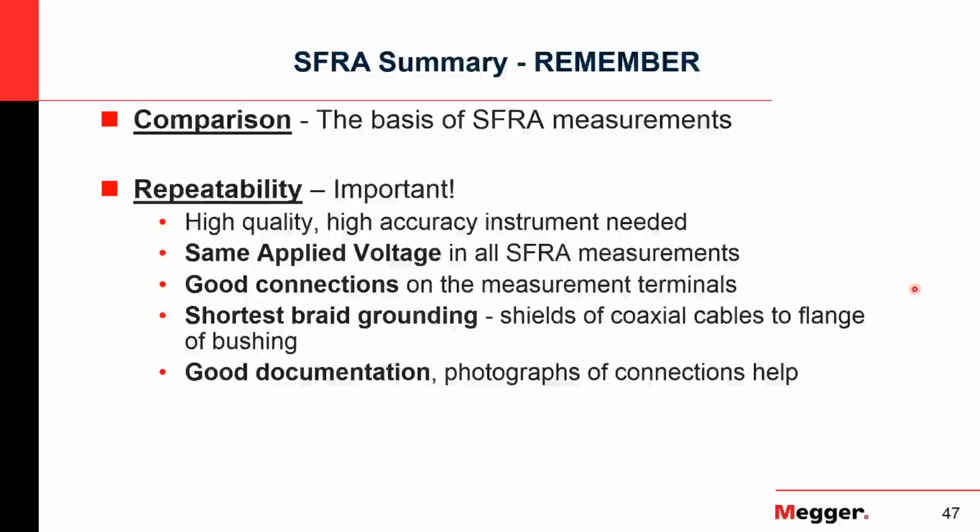And then also just good documentation. Make sure you note the tap position. Make sure you note if you didn't have oil or you had test bushings in there. You want to make sure all that's noted, so if there is a difference, you can see, no, we actually changed the parameters here. We're not comparing apples to apples, so you're not throwing yourself off there.